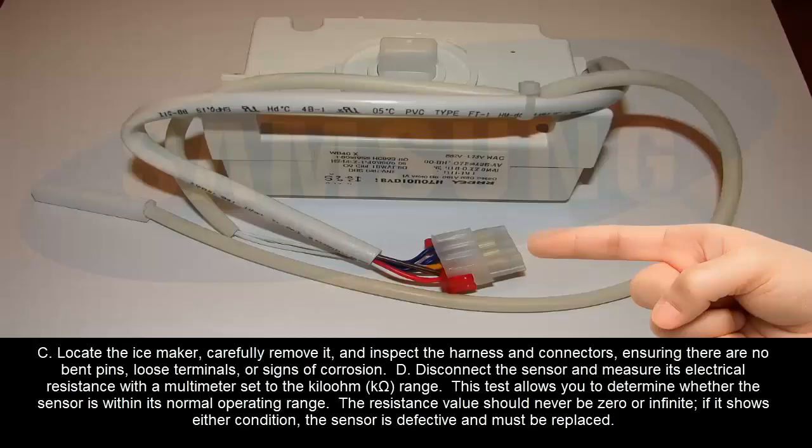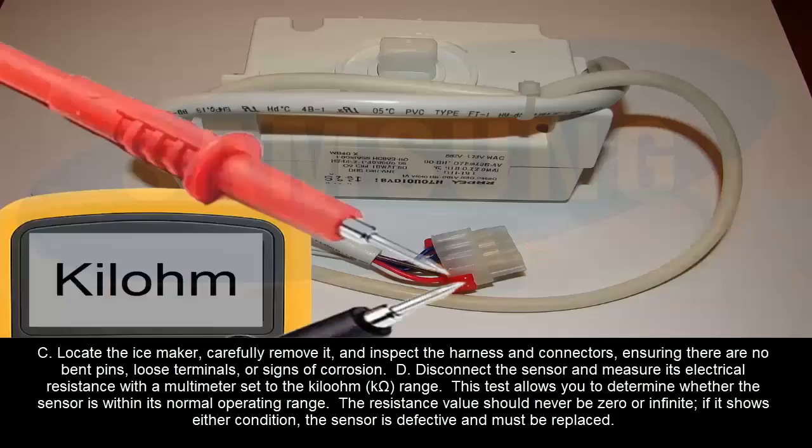D. Disconnect the sensor and measure its electrical resistance with a multimeter set to the kilo-ohm range, or kOhm. This test allows you to determine whether the sensor is within its normal operating range. The resistance value should never be 0 or infinite. If it shows either condition, the sensor is defective and must be replaced.